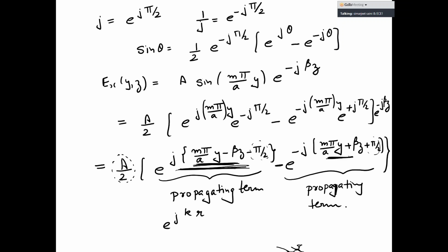So it's telling me that one term is not moving only in the z direction, it is moving in some yz plane. And the amplitude of this term doesn't change in that plane at all. That amplitude part remains like a plane wave, but the plane wave is not traveling in the z direction. The plane wave is traveling in some oblique direction in the yz plane. And if the plane wave in this case is going up, then the second term, the plane wave, is going down, but with very similar angles.